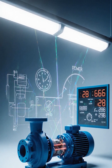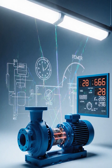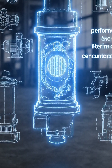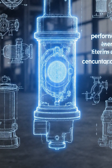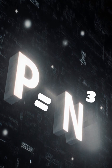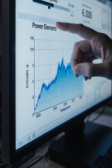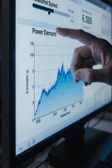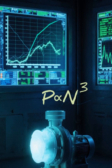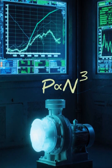The third affinity law defines the relationship between pump power and rotational speed. This law is fundamental in understanding pump performance and energy consumption. It states that the power required by a pump is directly proportional to the cube of its rotational speed. Therefore, even small changes in speed can lead to significant changes in power demand. The relationship between pump power and speed is defined by a cubic equation.